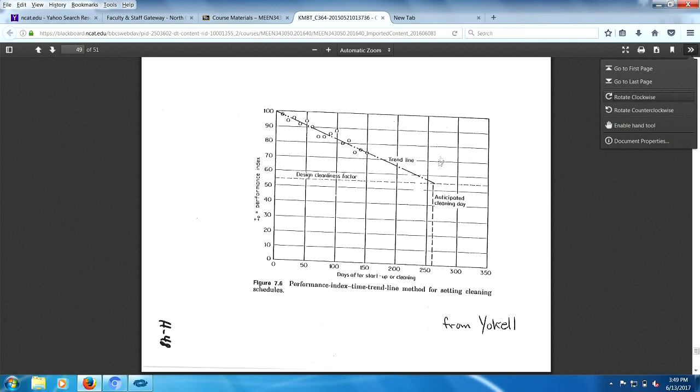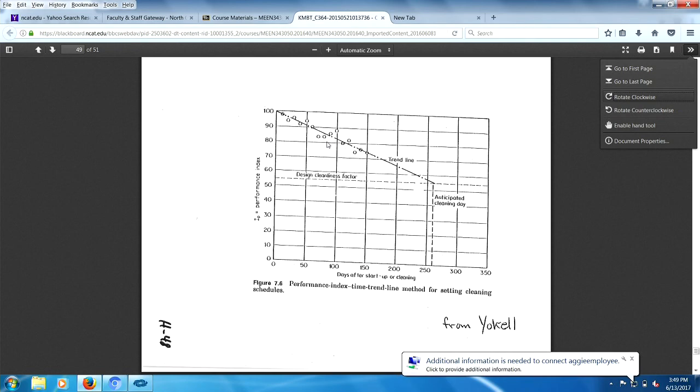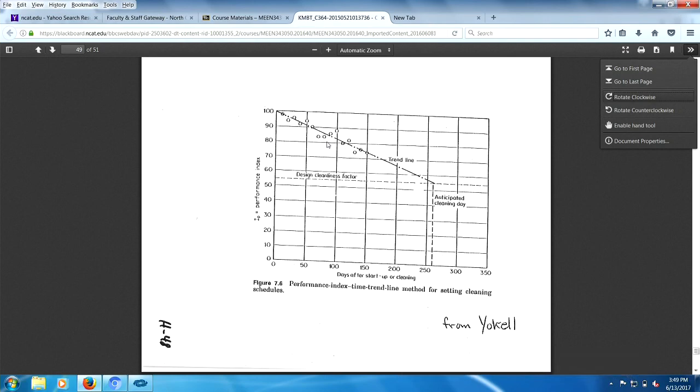Downtime means nothing's being made, so that's bad news. Then you start all over again after you clean. You want to take all the exchangers down at the same time, say August, or February, the time you clean heat exchangers, when it's not critical that you be up and running. You clean them all at once, and you standardize on one design used everywhere.